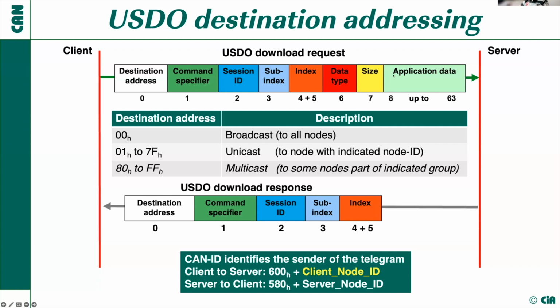And we now also describe the data. We don't just get something, but we describe the data, and I can map the application data and use the entire CAN FD frame, but only if we require it. If we don't require so much data, we can adapt it to the real needed payload.